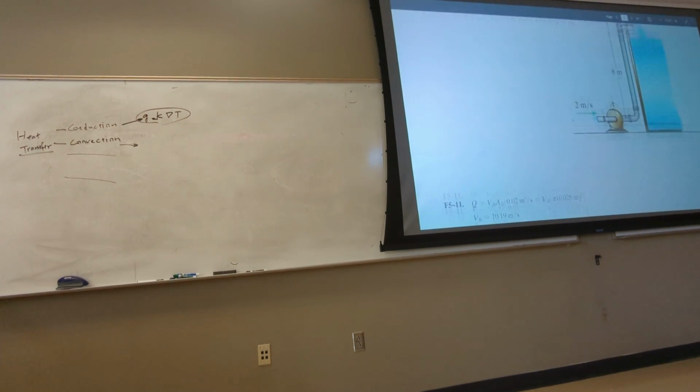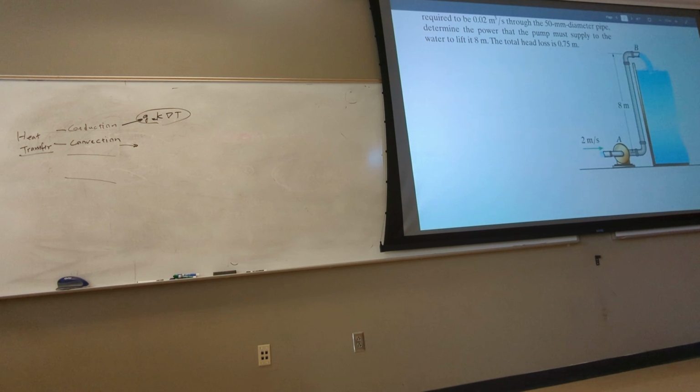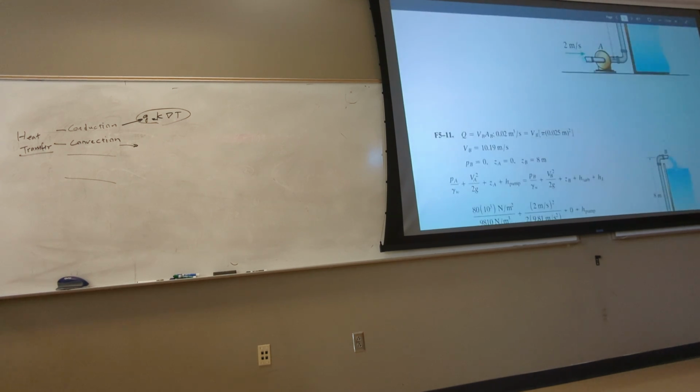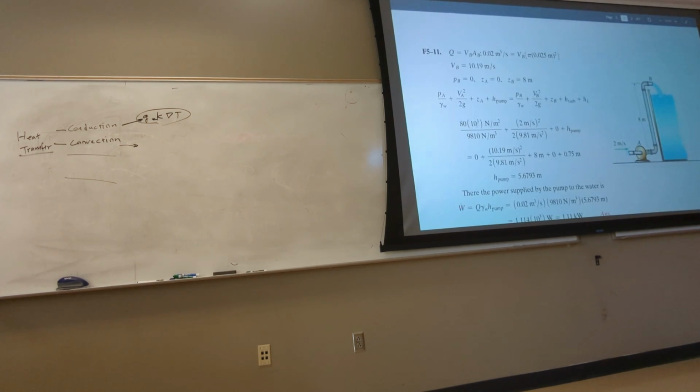So you just go ahead, again, once again you have a control volume, even though you don't go inside that, because you just see A and B. But you have a control volume from this point, and then this is the equation you have. You see that? The form I'm using, all the heads are written in meter. There is no energy, there is no joule per second. Right? But you should be able to convert this back to the m dot form, the energy form, if required.